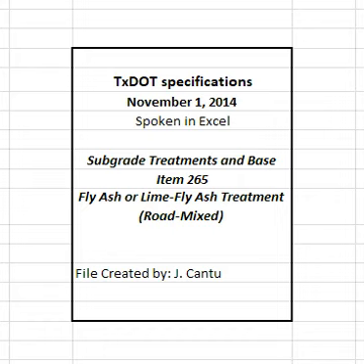After mixing and required mellowing, the engineer may sample the mixture at roadway moisture and test in accordance with TEX-101-E, Part 3, to determine compliance with the gradation requirements in Table 1. Table 1. Gradation requirements, minimum percent passing. Sieve size, base, and subgrade. Sieve size 1 3/4 inch with a base of 100% and a subgrade value of 100%. Sieve size 3/4 inch with a base of 85% and a subgrade value of. Sieve size number 4 with no base value and a subgrade value of.